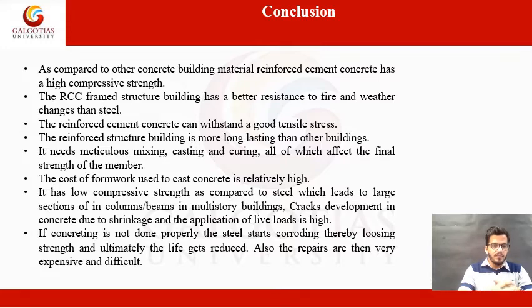It has low compressive strength as compared to steel, which leads to large sections of columns and beams in multi-story buildings. Cracks develop in concrete due to shrinkage and application of load when the load is very high. If concreting is not done properly, the steel starts corroding, thereby losing strength, and ultimately the life gets reduced. Also, the repair costs are very high and very difficult to do.